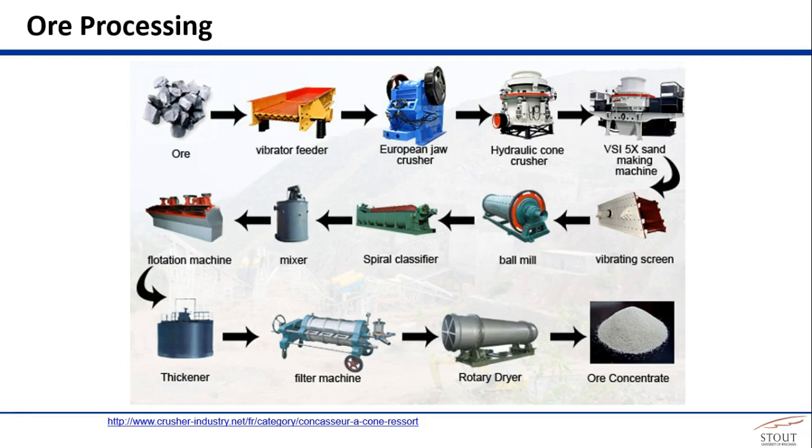They then skim off that froth and dry it down, and it turns out that differential sedimentation by flotation is one of the most effective ways to separate things like copper ore from the silicates. And so it's literally like bubbling in your milk, except with purpose. By skimming off that froth and drying it down, they can isolate copper. Thickened, filtered, dried, and finally an ore concentrate that's then advanced to the next step.